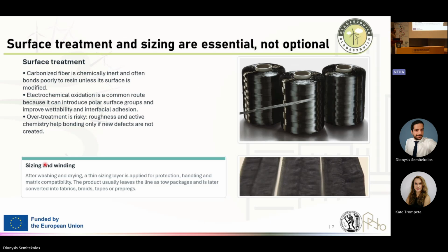Again, in the lab, we have developed several approaches to size the fibers. You are going to see them today, later in the lab. We have a pilot line to continuously size our fibers. During the industrial process, sizing is used to apply a thin film on the fiber surface, mostly to protect the fiber from environmental damage, and also to facilitate handling of the fiber by workers.